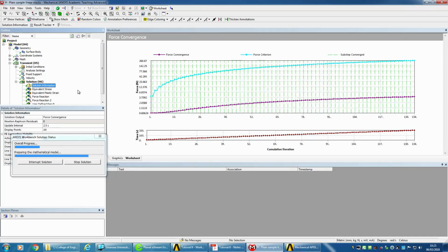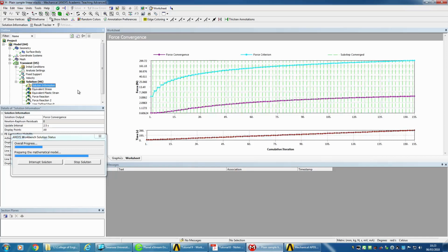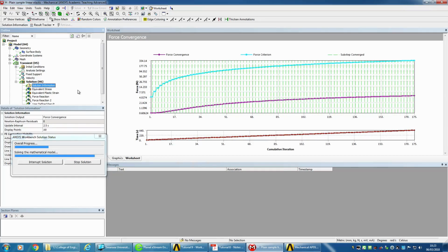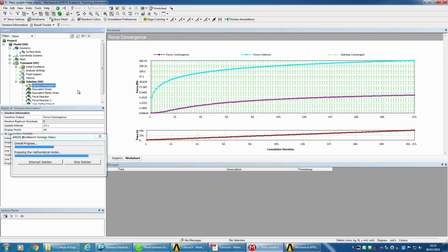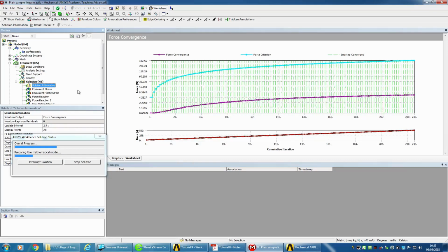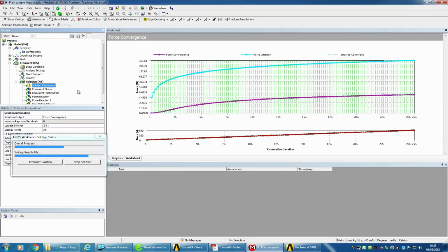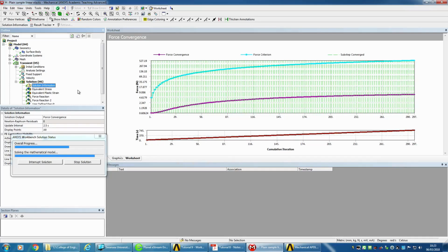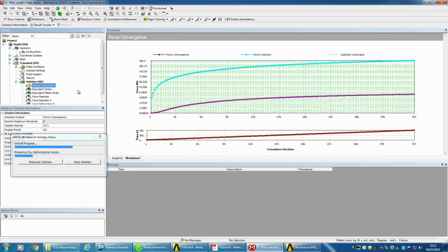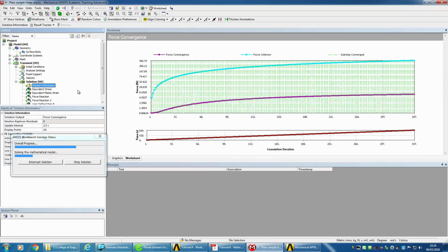What you can see on the convergence graph here is that you've got a lot less variation, because what's happening here is we're solving the linear elastic problem. There is no nonlinearity. That lack of nonlinearity means that we have a lot less convergence problems. So you've got a pretty smooth convergence curve, and as you would expect, there's no problems with convergence. But actually it's that very lack of problems with convergence which tells you we've got no upper limit. There is no upper yield strength.